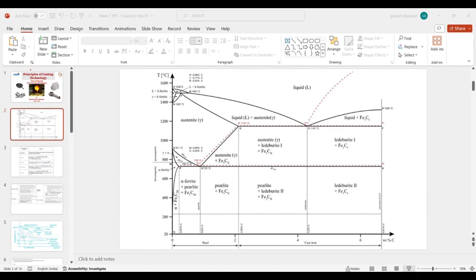Yeah, you can say you have to homogenize that whole sample. In surface heat treatment you require some extra additives during the heat treatment process, but in normal heat treatment processes you just have to put your sample in the furnace and cool it down according to your need, either annealing, quenching or normalizing.